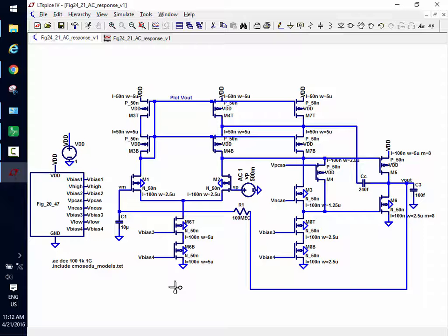Okay, so if I ask what is the output swing using this topology, it can go very close to VDD and ground. Does everybody see that? But the input diff amp can't, can it? It can only go to a VGS plus a VDS sat and then basically up to VDD minus a VSD.